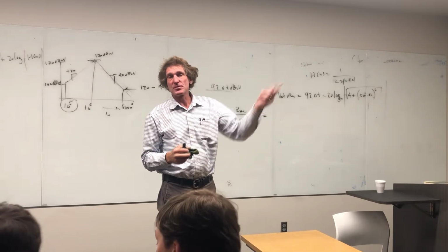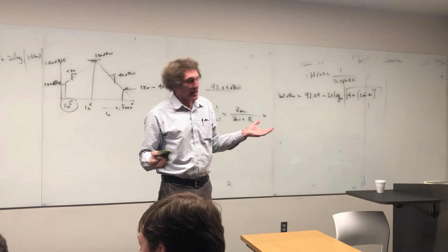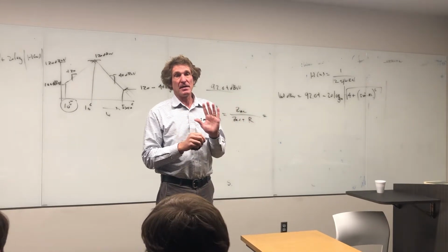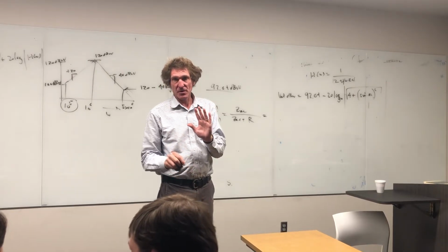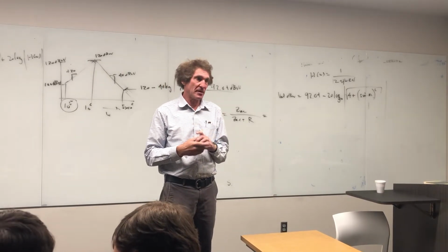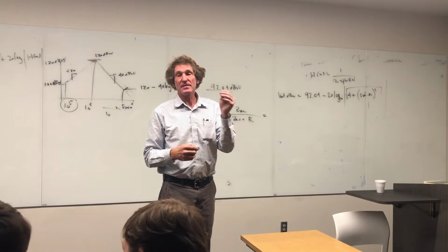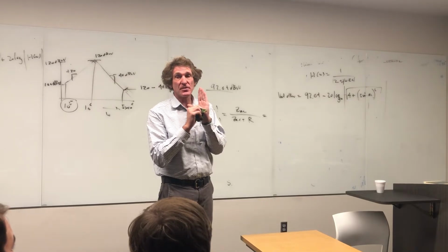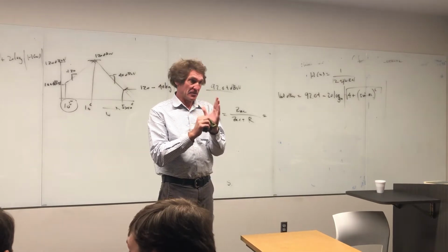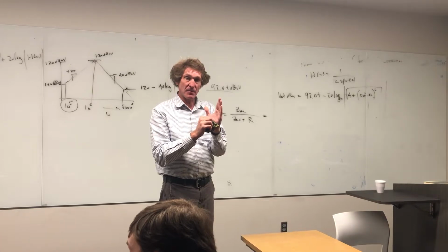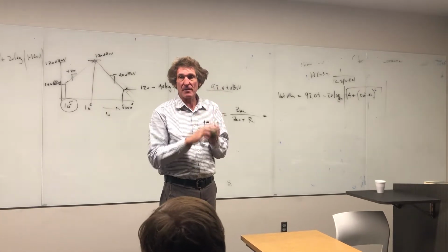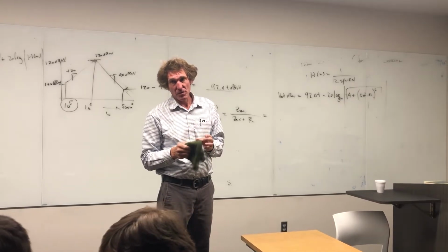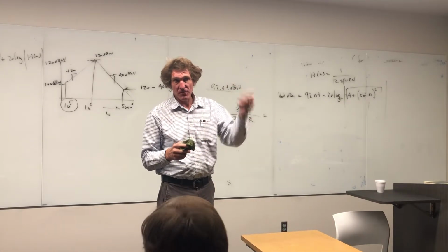Our electric field is volts per meter almost all the time, right? The real world stuff, they take dB microvolts per meter. So if you had an E field of 10 volts per meter, it would be 20 times the log of that E field divided by 10 to the minus 6. That's the way they usually talk about electric field values in the real world when they're talking about any type of radiated emissions, conducted emissions, and for that matter, when you're doing sensor work and a lot of antenna work. So it's dB microvolts per meter.